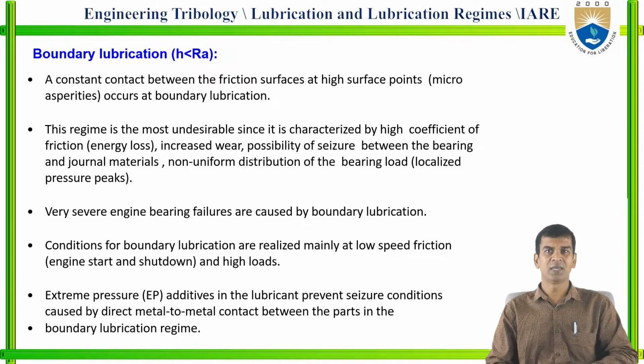The condition for boundary lubrication is realized mainly at low speed and high loads. The remedy for boundary lubrication is the addition of extreme pressure additives to the lubricant.